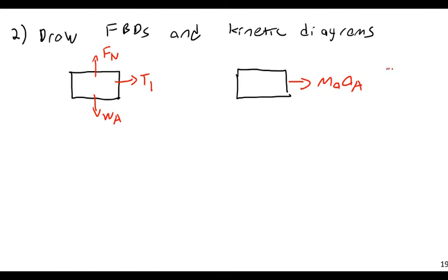Again, I know it's going to accelerate in this direction, because if this thing is being driven by gravity, the only way that this thing can move is if this block moves to the right and block B moves downward. Now, I could actually force it to go the other direction if I pulled on this block with a great force, but they would have to tell us that force. They could say it's moving at this acceleration to the left or something like that, and we could calculate other things. But if this thing is only moving under its own power, the only way it can move is downward for block B and to the right for block A.